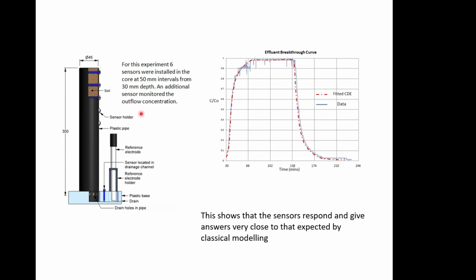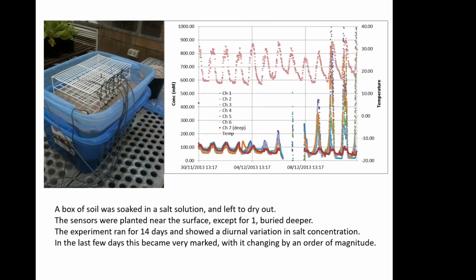So we got a good idea that the sensor was working, was detecting chloride, detecting the right amount, was nicely calibrated and worked. And then we went out to a field. Well, we went to this box, which was actually a box in Australia in a greenhouse, and did some experiments here by filling up a tub full of sandy soil, putting salt into the solution, pouring water into it, drilling some holes in the bottom to allow it to drain out, and left it for 2 weeks. And took measurements, and these are 24-hour periods, so we can start to see the days involved here, and took lots of measurements. And these are the responses of the sensors, which are buried in the soil here, going along.